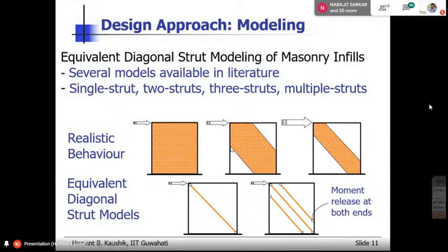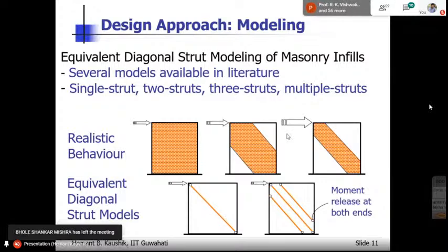So that is why you will find that some type of damage may occur to the column. In this case, when you have the contact area further reduced, the damage will be here and damage will be more in this region, right? The reason is the axial force has increased. Though the area has reduced, the force has increased. So the point is, can we model this damage to the column, the failure that may occur in this column, using single diagonal strut? The answer is no. We cannot model that type of failure, that type of damage to the columns using single diagonal strut.